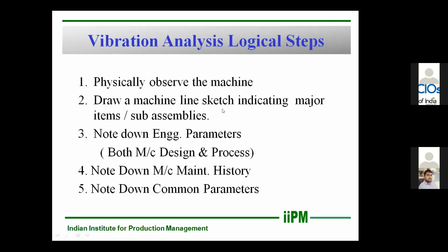Then draw a machine sketch indicating major items and sub-assemblies, and note down engineering parameters, whether pressure, temperature, everything you need to know. Then note down the maintenance history, because you do not know what maintenance has been done before, and you are going to analyze that machine. You will not get any clear idea, just like a detective.